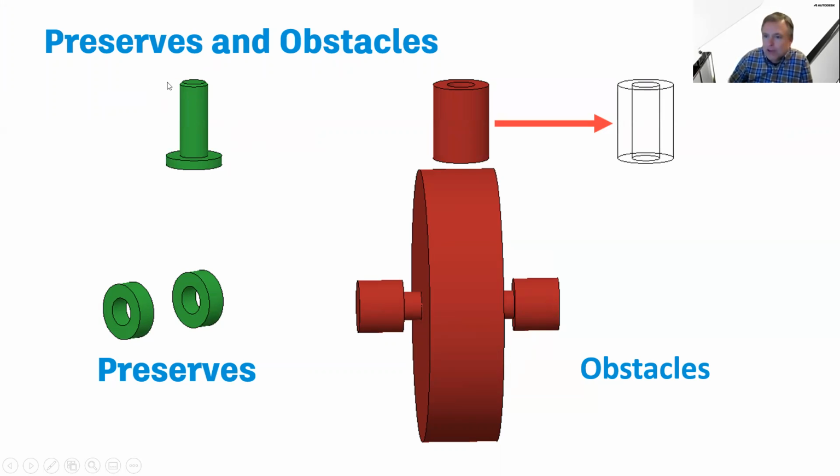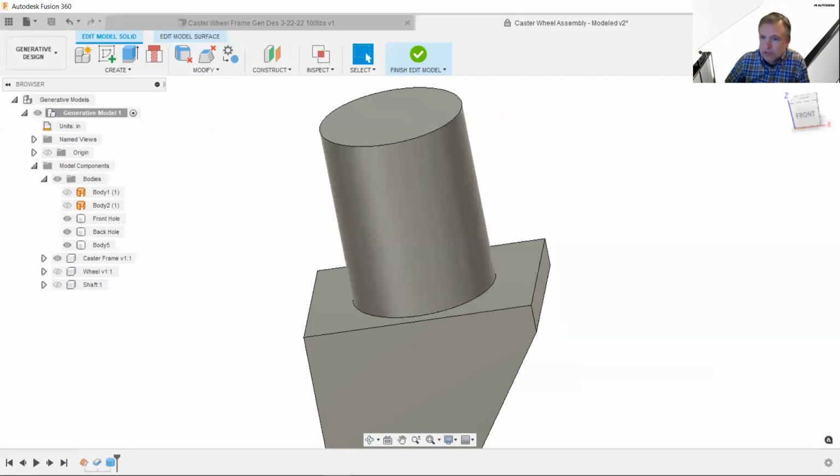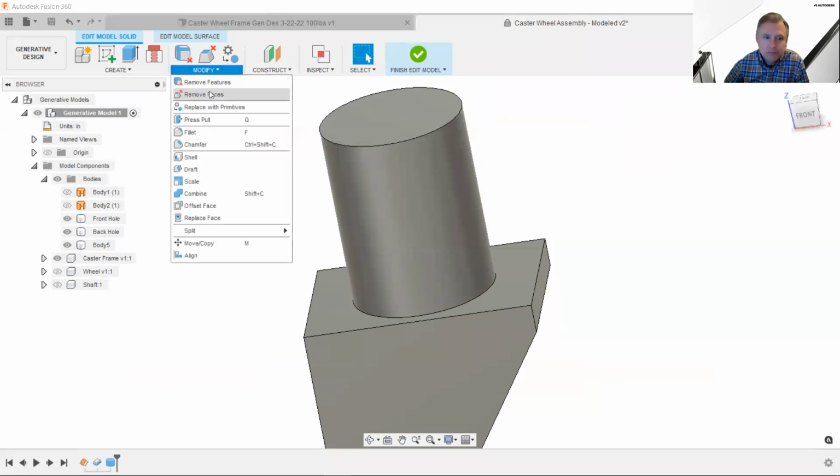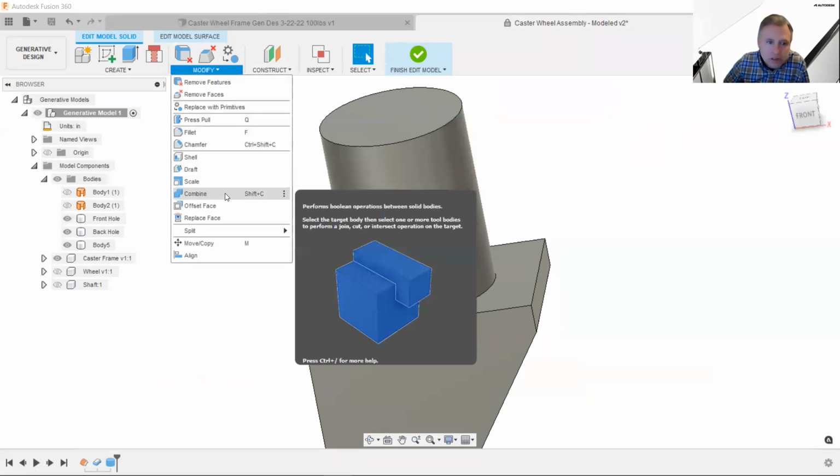All right, so we just created that top level cylinder, which encompasses it, but I really want to be left with this. Has anyone ever used the combine tool inside of Fusion before? It's awesome, right? So here's the deal. From the modify menu, what are we, 6 tools from the bottom? Combine, go ahead and click on the combine. So again, this combine, this is our Boolean operation.